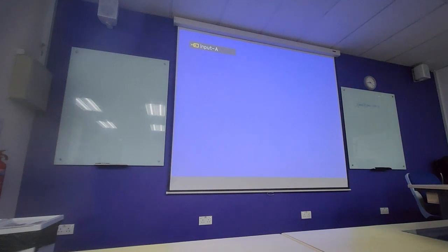Right. So the compressor runs, then pumping air into the tank, right? So you will see pressure increase. Let's say the compressor is off, meaning there's no pumping into the tank, right? You will see, because of the demand, the workshop needs your air, so the pressure inside the tank decreases. Right, so from 790 it will slowly go down, until 690, it comes on again, right? And after that, 790, then it will go off. But let's say you still have the workshop, you need that air, then you will see the tank deplete again.